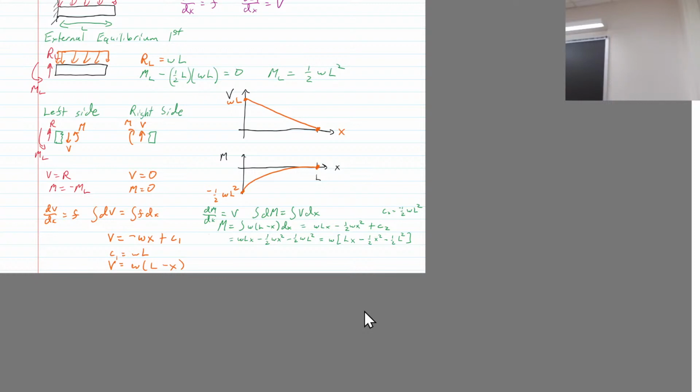If we're looking at that face, it's a little bit confusing. If you scroll down to the next slide, we say these are the contributions from Py, and this is going to be tau xy. That's also a little confusing. We're looking at the x. If you draw this, tau xy should be positive, since the x is coming out of the beam. So tau V is contributing positive tau xy, and tau T, as we're calling it, is contributing minus. This one is from the transverse shear stress, and this one is from torque.